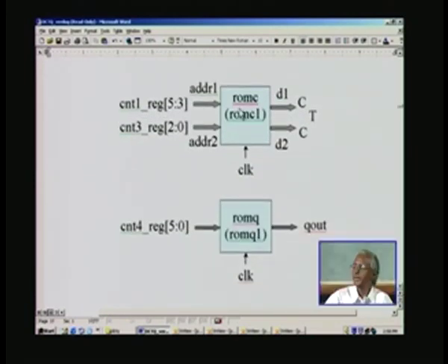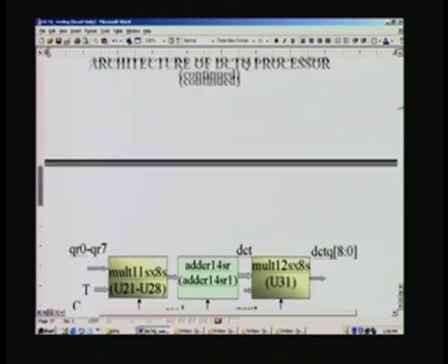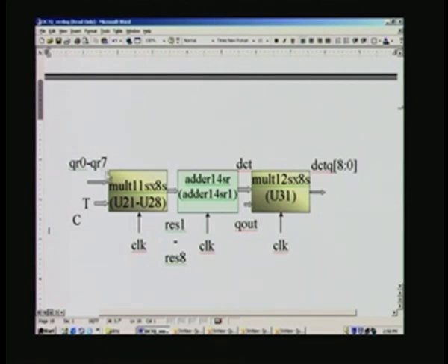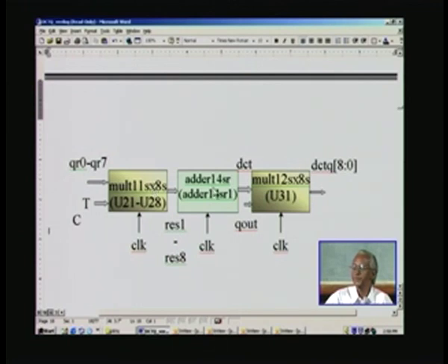So, this delay need not be reckoned because it is a parallel affair. So, how much did we count? 23, and that is we are looking at only the data flow, right. So, here once again 8, 23 plus 8, 31, then 6 here because a register is involved. So, how much does it come to? 37, right, 37, and once again one more multiplier is there which is 8, so 45. So, out comes DCTQ only after 45 delay.